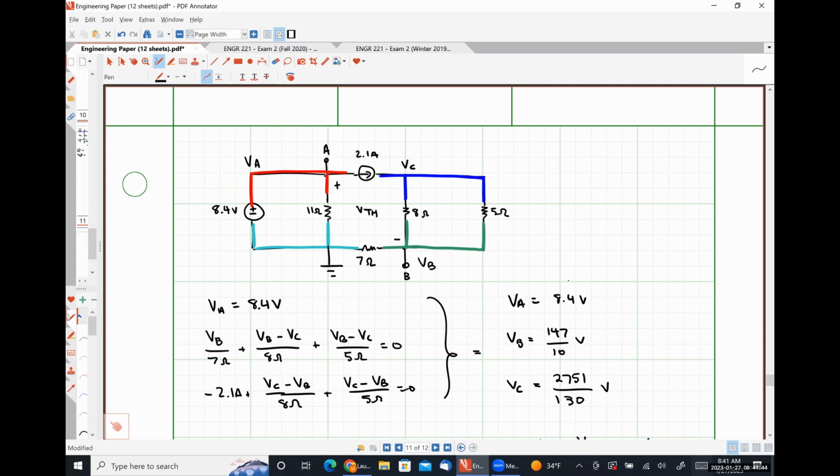Two reasons, really, they're kind of the same thing. So we have a supernode that contains our voltage source, right? Because anytime we have a voltage source and we're doing nodal analysis, we are going to have a supernode. Because our supernode contains ground, we don't write a KCL equation. If they didn't contain ground, yes, we would, absolutely. So with the original choice of ground, we would have found the 11 ohm resistors showed up in our equations.